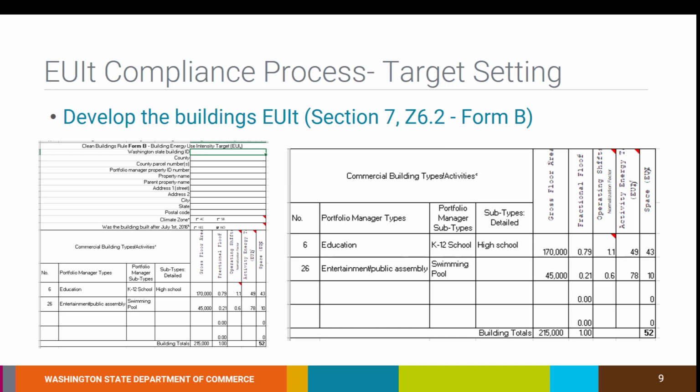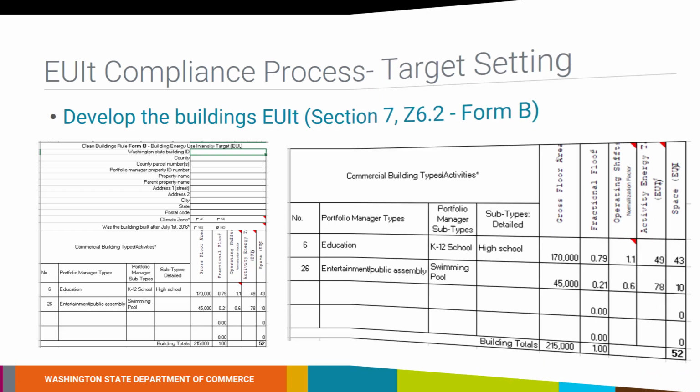If initial benchmarking identifies that the building's weather normalized EUI does not meet the EUIt, a qualified energy auditor shall complete an energy audit according to the requirements of Section 8, energy audit requirements. After the energy audit has been performed, EEMs identified in the audit that will reduce energy use to or below the EUIt shall be implemented in accordance with Section 9, implementation and verification requirements.